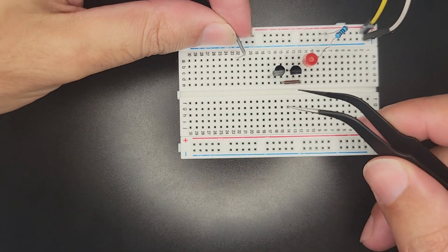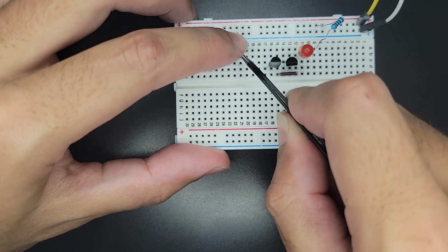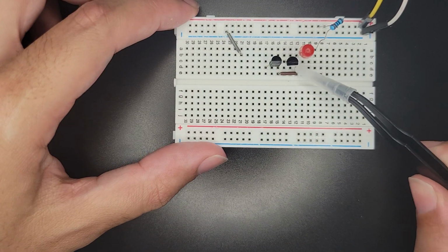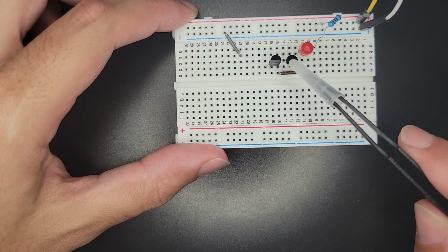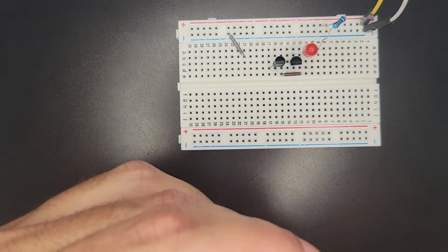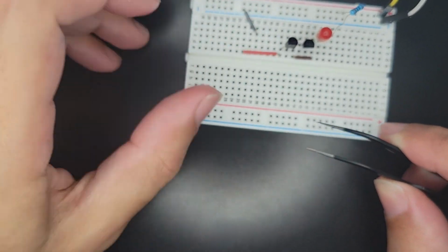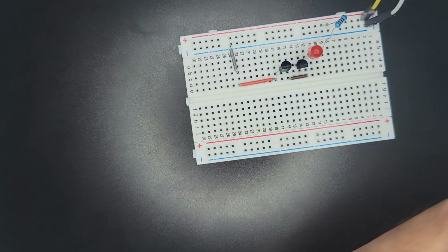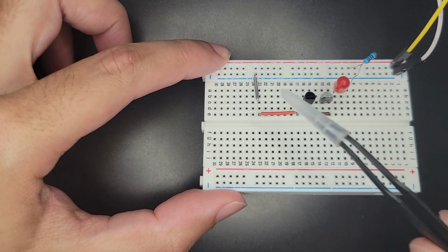All right, let me tie down the ground. Give ourselves somewhere for ground to access easily. Bloop. So this is ground. So right now we have our current going up resistor into LED into both of these guys. And we're just trying to find a way for them to get home. They both want to get home. They want to emit. So I'm going to add another little wire here. Let me tie this one over to connect them all. So right now, transistor B has a way for their emitter to go home.